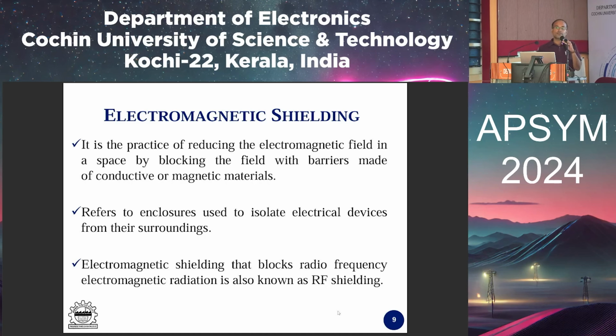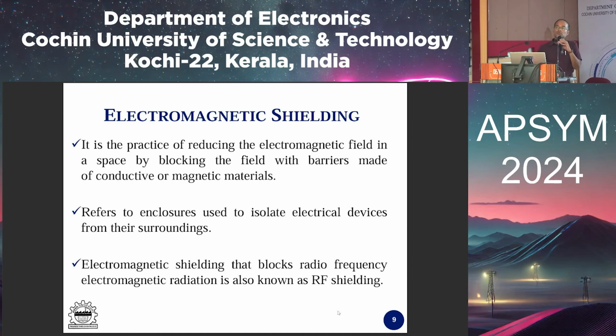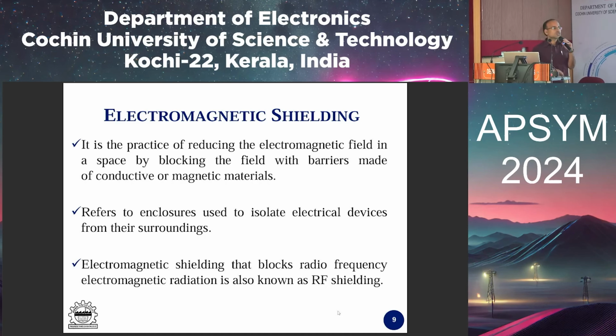For example, when we go for any antenna design, if I want to characterize it, we go for an anechoic chamber. A chamber is the best example where we can say it is shielded from the external environment, as well as the radiations within that chamber are not going to be released, or we could say, are not going to disturb the external environment. To realize that, we go for this kind of FSS.